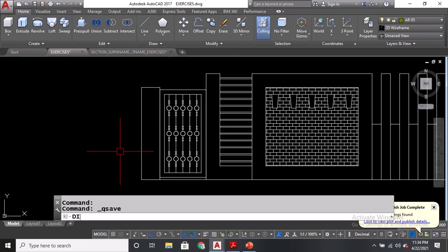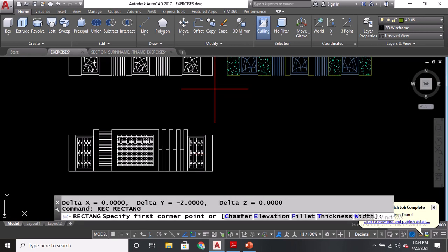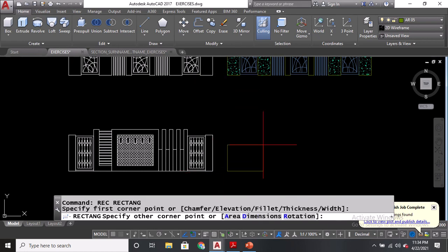Start natin siya dito. So, let's see. This one is 0.4 by 2 meters. Okay. So, that's our EC ulit. I'll just track the endpoint here. Hindi ko siya i-click. Itatapat ko lang yung endpoint ko. Okay? Again, hindi ko i-click. I'll just be hovering it. Slowly guide it downwards. Tsaka dito. There you go. Then just type at 0.4, 2.